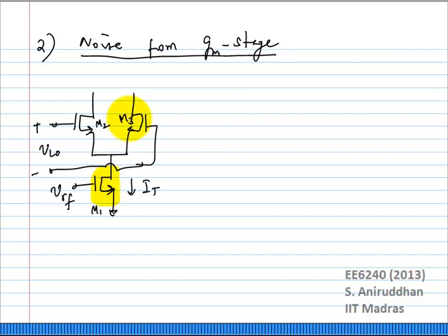So the noise here, the noise produced by VRF, as far as the transfer function from the input to the output, cannot be distinguished from the RF signal. Right? Whatever happens to the RF signal or whatever happens at the RF port, from a signal point of view, will be indistinguishable from what happens from a noise point of view. For example, if I had said it had some noise here, what would you have told me was the transfer function? If I had VRF, what do I get at the output?